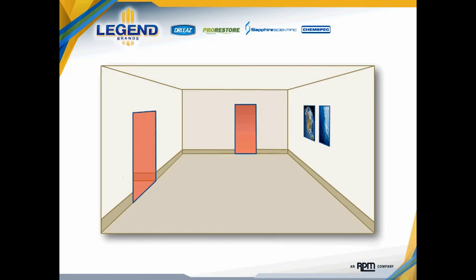So the air movers that we looked at earlier for installation would also need to be installed in those same areas to ensure that we were pulling moisture, temperature, and humidity out of these rooms, delivering it into the next room, moving that temperature and humidity throughout the space, again delivering it to this adjacent room, then pulling it out of this space, and using this entire wall assembly to bring that same circulation of air back to its point of origination. And when we generate that type of circulation, then it does not matter where the dehumidifier is installed.